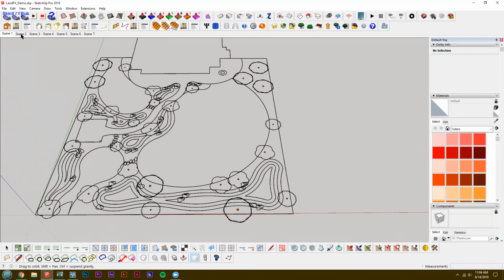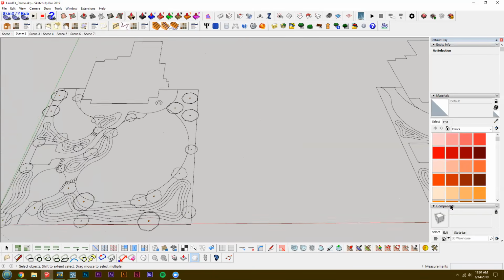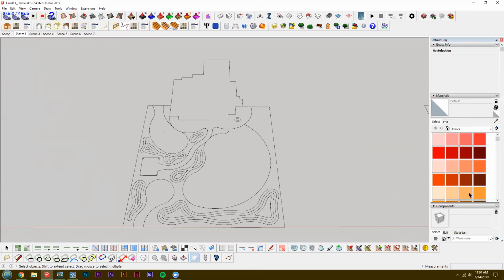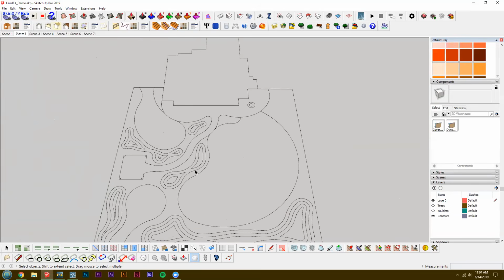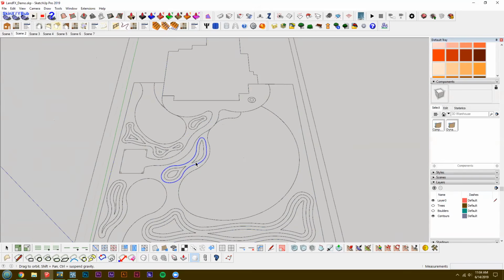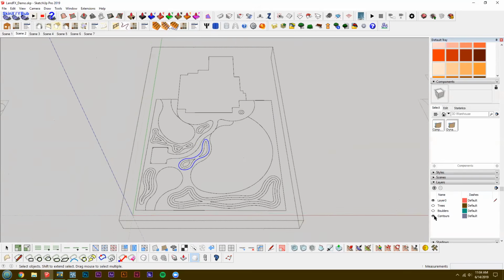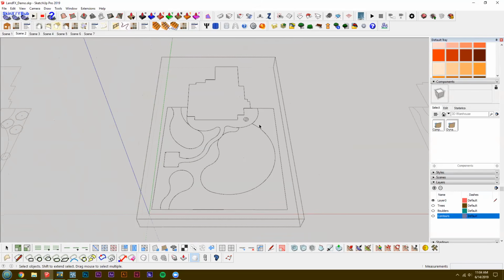And so the first thing I like to do is go ahead and clean it up a bit, put everything in its own layers, go about welding the lines so they're all one continuous line. And then once that's all complete, I like to run an extension called Make Face, and it saves a lot of time. I don't know how long the delay is for the webinar.